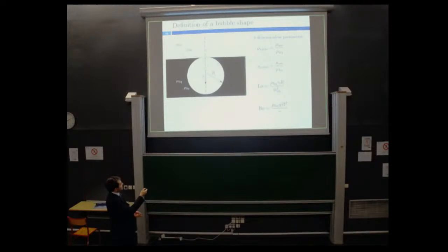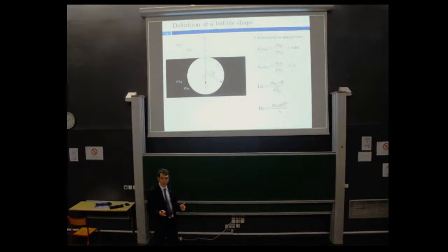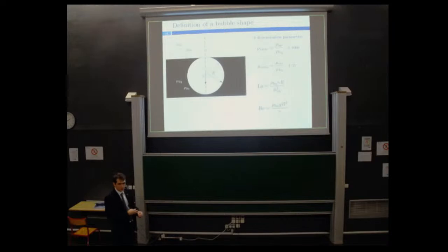We start with the density ratio and the viscosity ratio, comparing the density and viscosity of air with the density and viscosity of the liquid. Those ratios are taken close to the density and viscosity ratio of air in water, and they are high enough to consider that they will not impact the bursting bubble process. We will assume that they stay constant during this entire presentation, and we will not change them at all.